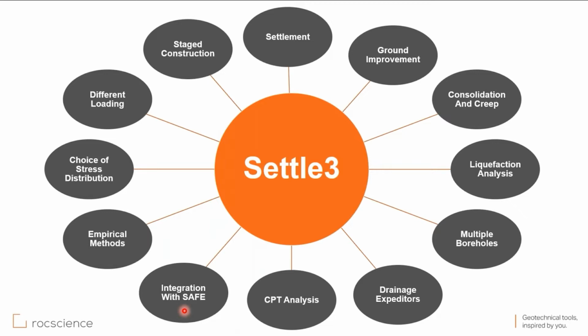loads. Also, within Settle3 we have empirical methods you can apply. You can have different types of loading. You can have different choices for stress distribution. And one of the most important features is the staged construction. You can load in stages and unload in stages, with time, and you can get the settlement through these stages.